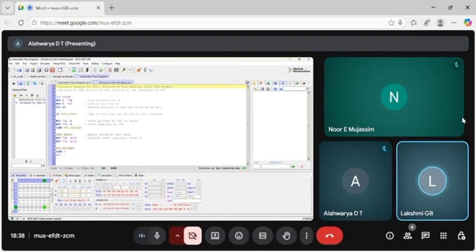If B equals 0, then the OV overflow flag is set, division by 0. Check for division by 0: JNB OV or JZ error. If the OV flag is set, division by 0, jump to the error label.